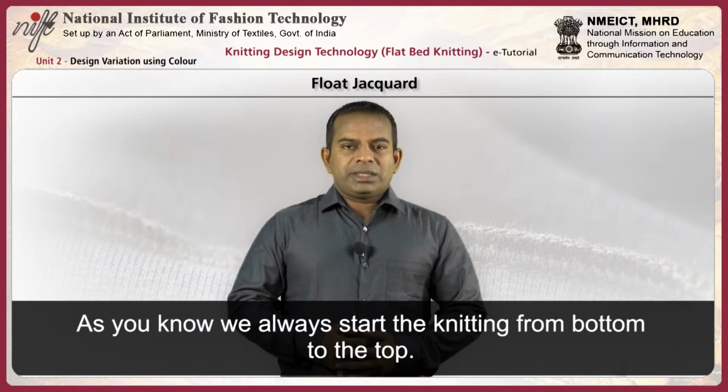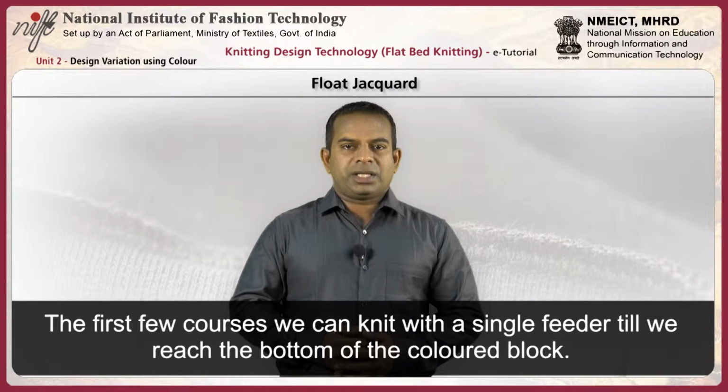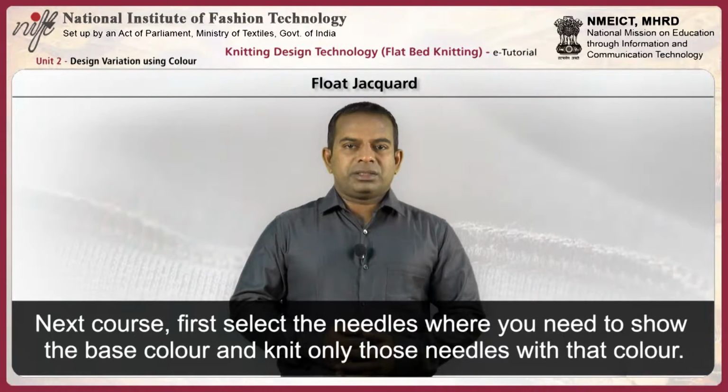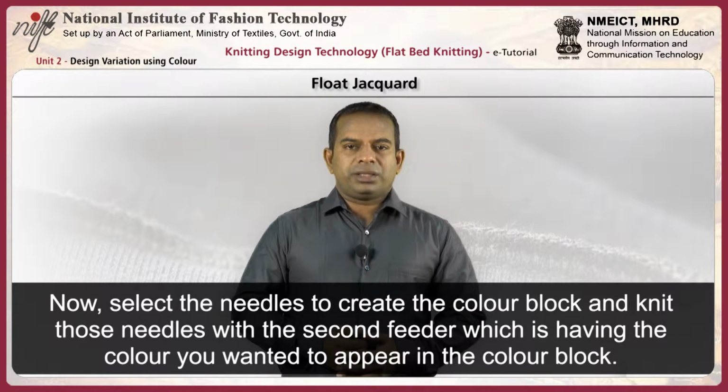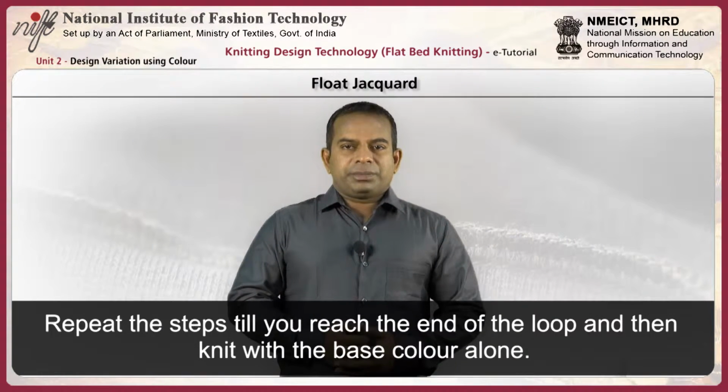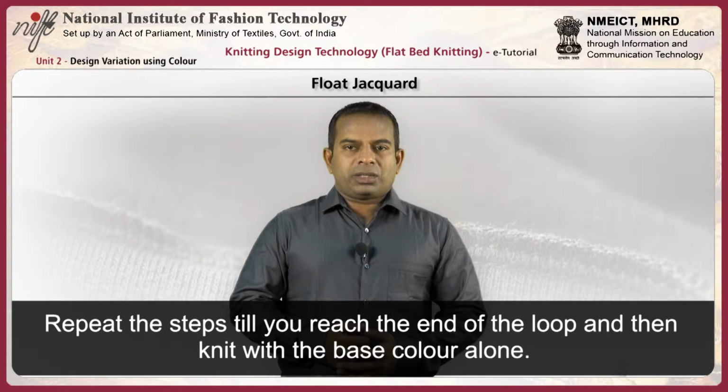As you know, we always start the knitting from bottom to the top. The first few courses we can knit with a single feeder till we reach the bottom of the colored block. Next course, first select the needles where you need to show the base color and knit only those needles with that color. Now select the needles to create the color block and knit those needles with the second feeder which is having the color you wanted to appear in the color block. Repeat the step till you reach the end of the block and then knit with the base color alone.